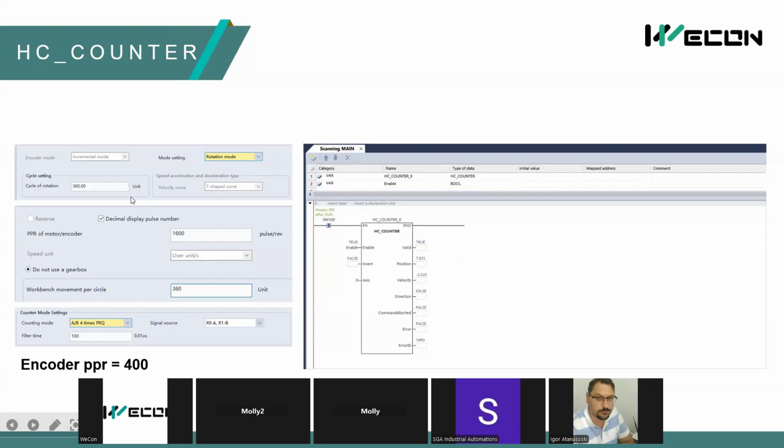And this is the axis configuration of my environment. Here I set the mode as rotary mode, and the cycle is 360. And this is the user unit. First, the PPR of my encoder is 400. It's an AB phase input signal. So here I select counting mode as AB phase and I connect phase A to X0 and phase B to X1. Because it is four times frequency.